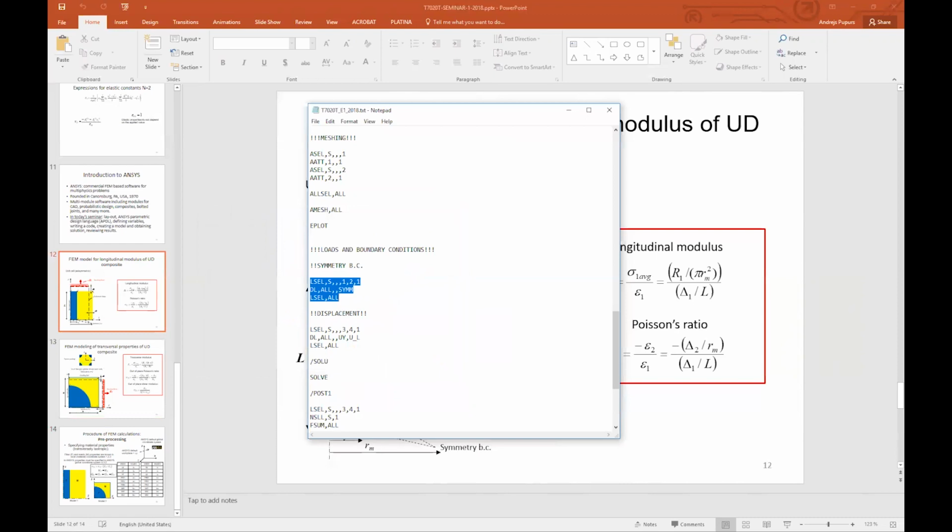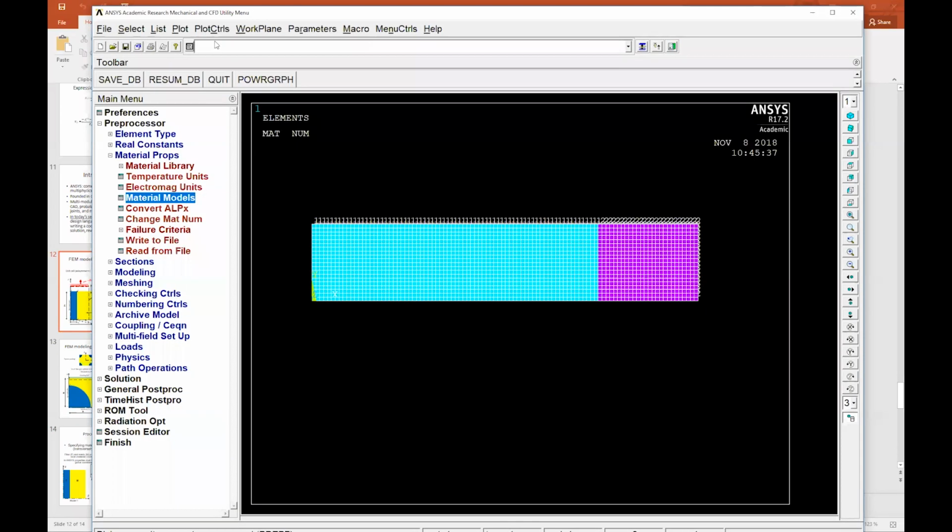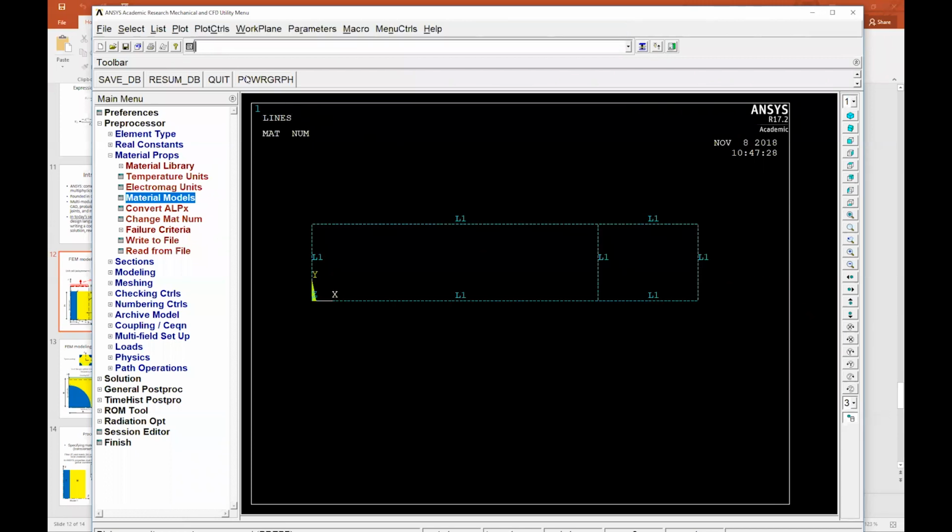I will just copy paste this so that you see. Okay, I'll plot the lines, but if I copy paste these conditions of symmetry, then what is visible on the interface is that you have the letter S here appearing where you have applied the symmetry conditions.